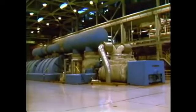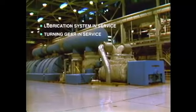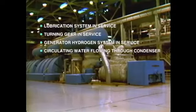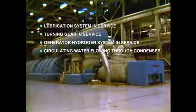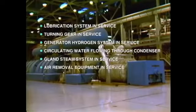Summarizing then, the following conditions must be established before steam can be admitted to the turbine. Lubrication system in service. Turning gear in service. Generator hydrogen system in service where applicable. Circulating water flowing through the condenser. Gland steam system in service, providing sealing steam. Air removal equipment in service with vacuum established in the condenser.